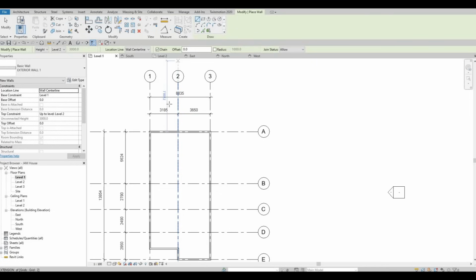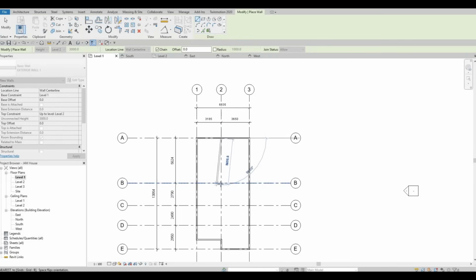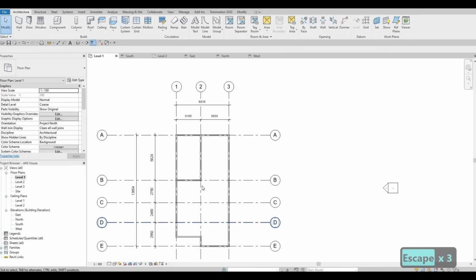Once you click that, you'll be able to select whatever object right here, and you can add it again. So here I'm going to add an exterior line for A2 up to B2 and going back to B1. So now we have exterior side and exterior wall right here.